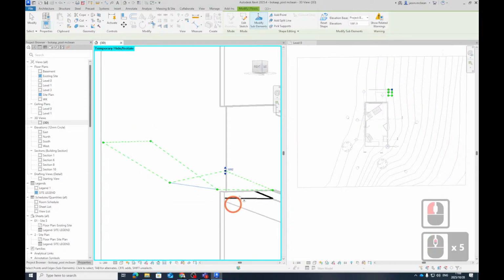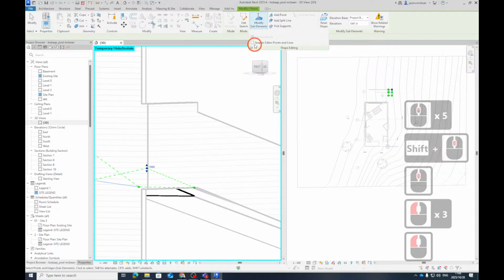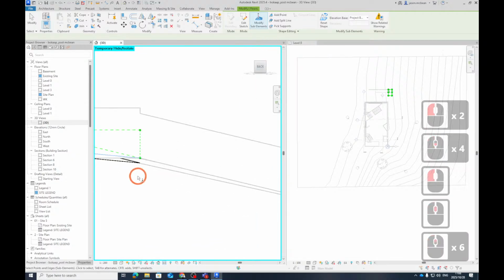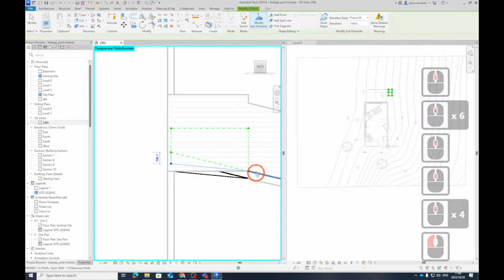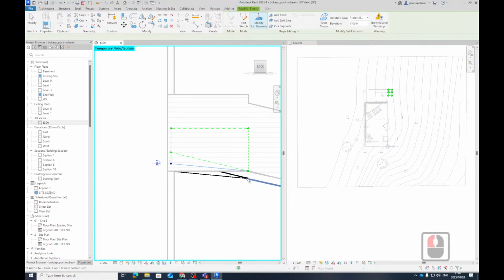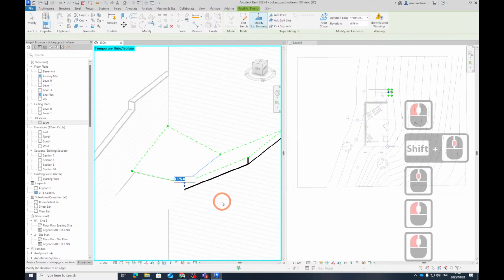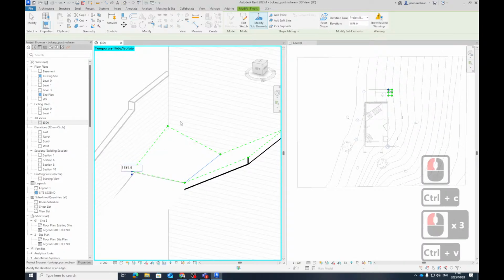So you can move these and snap them. So you want this enabled. Enable snapping to lines. Okay. You actually want to work on a bit of a side view. Okay, sometimes this is a bit strange. But you can also copy that value. Control C, yeah, just paste. Control V, that's actually the safer bet.